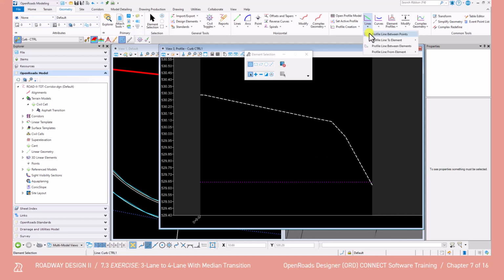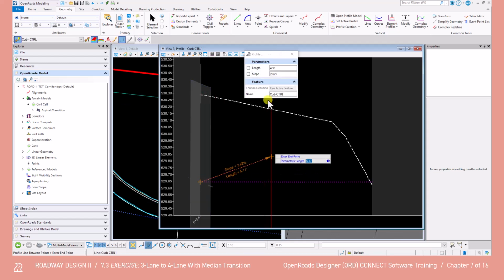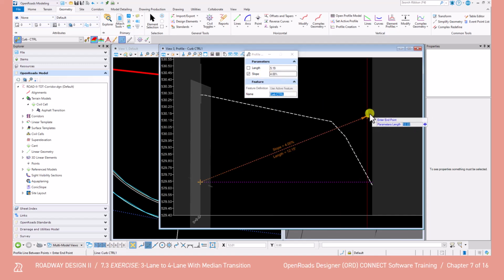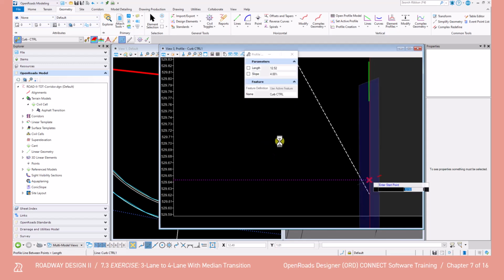Before left-clicking to accept the snap to the end of the blank area, tap through the inputs until you see the slope input and key in 4. This should lock the element into a 4% slope. Repeat this procedure starting at the right end and key in -4, this time for the slope.